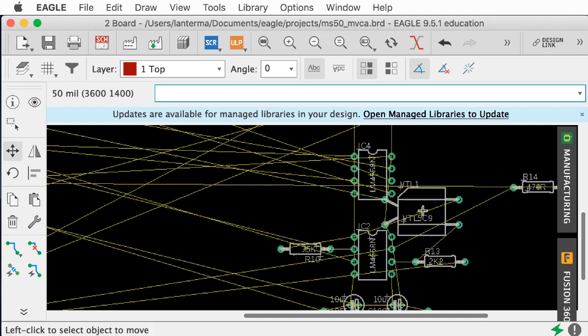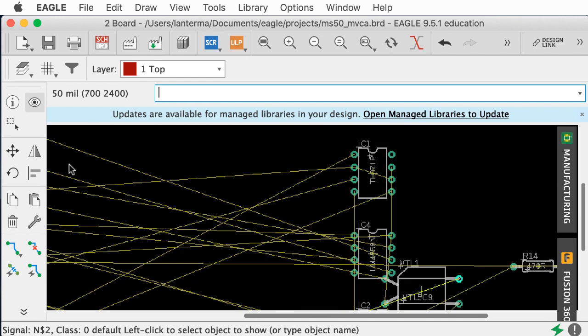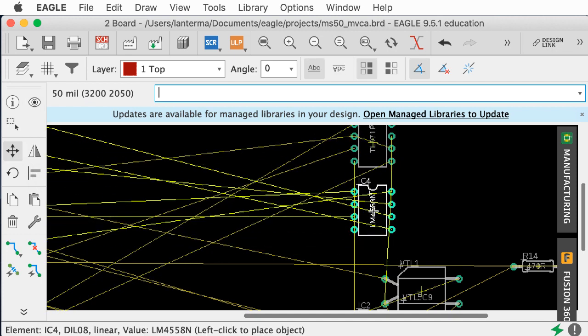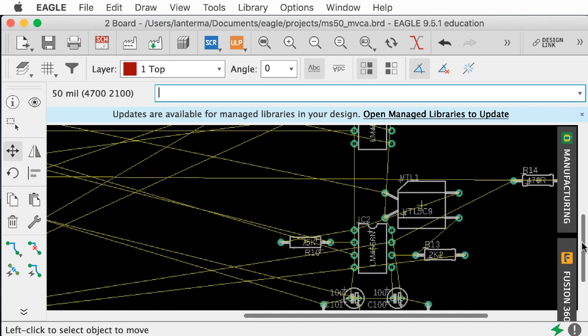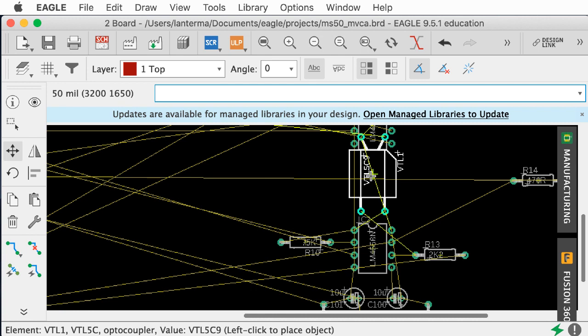Now which one is actually the resistor part and which one is the LED part? So this guy down here, I can type show and I'm going to click on this guy just to see what connects. So this all connects. So this is part of that resistance network, as is this. Notice that the Vactrol sort of spans the two op amps on the two different sides of the chip. So what I want to do is make that a little more explicit. I'll move these guys up a bit. Let's take the Vactrol and sort of make it the centerpiece of the operation.